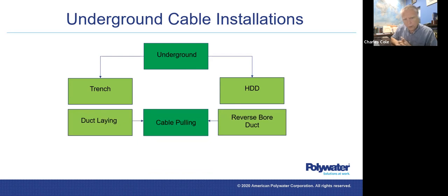So when we're installing cable into a duct, we're calling that cable pulling as opposed to cable laying. We would be laying the duct in the case of a trench, but not the cable itself. One of the terms that I hear a lot in India is cable laying, and that defines, from what I understand, both cable laying in an open trench as well as cable pulling through a duct. So I'm going to differentiate those terms by using the term cable pulling when the cable is being installed into a duct. Next slide, please.